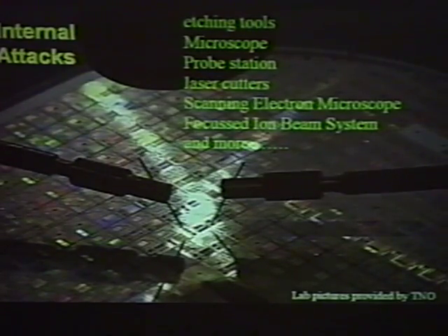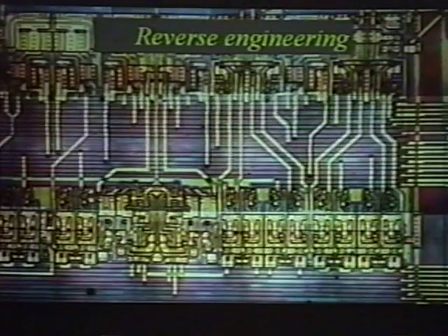So we can direct a beam of material, and it can be metal or isolation, and this is, I would say, the perfect reverse engineering tool for making changes to a chip. It's quite often used in prototyping when manufacturers design new chips and there are small problems. They use a FIB to change the circuits. And, well, there are more tools. Let's see a couple of pictures.